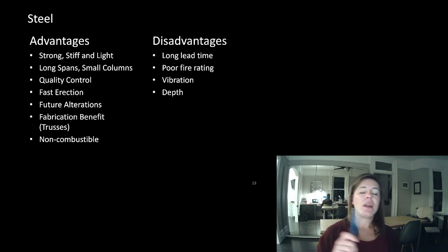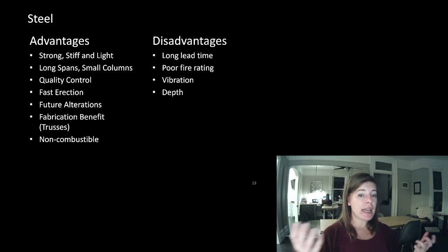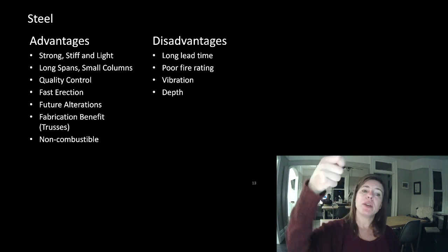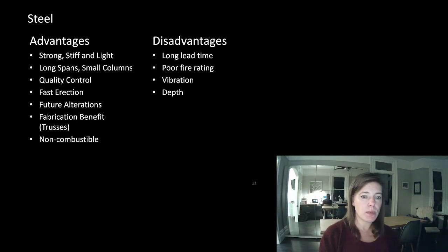And then when it's being erected on site, the steel goes up and it's kind of sitting there exposed with most of the elements up, where you can go in and with a tape measure I can be like, yep, that's a 150, that's what I wanted. Oh, look, you're missing a few bolt holes there. That doesn't look like the moment connection it's supposed to be. So it's really easy to visually see if it matches what the structural drawings were.